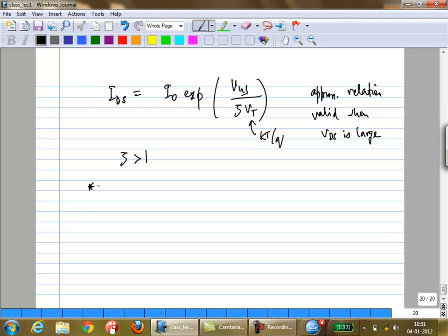And when do you have to worry about this? You have to start worrying about this when, obviously, VGS minus VT becomes very small. So when your overdrive, VGS minus VT, starts to approach maybe 40-50 millivolts, your transistor most probably is in subthreshold or very close to it.